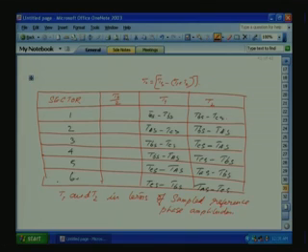What is the advantage now? If the sampled reference phase amplitudes, that is our VA, VB, VC, are known, multiplied each one with TS by VDC, you will get the corresponding fictitious timing in each sector, and by simple subtraction, you will get the T1, T2 in each sector. So, this is very easy to find out. Let us see what is the meaning of this. Let us find out TAS, the sampled reference phase angle, and how to do it. Let us go to the next sector.